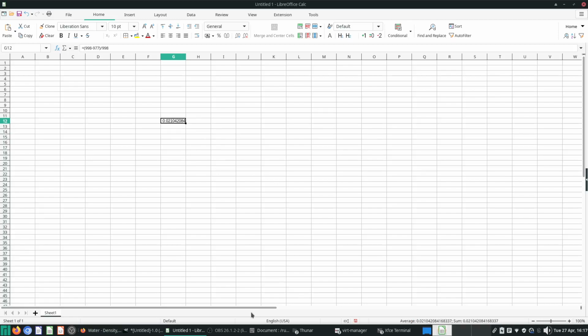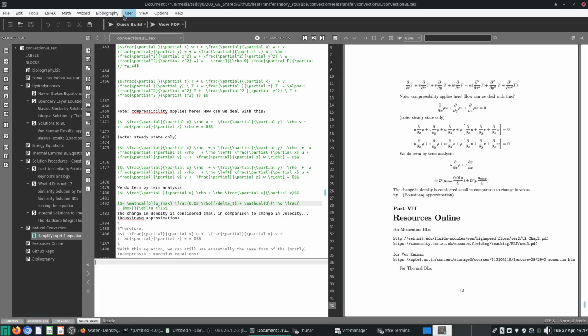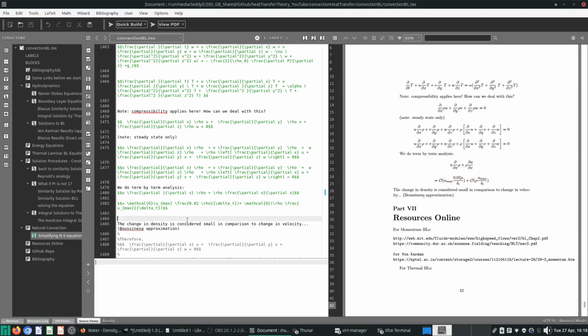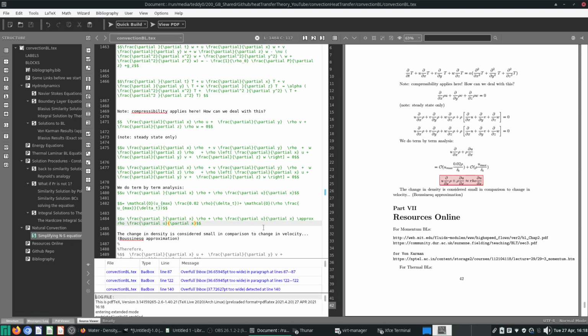It's not completely negligible, but compared to this term over here, you can just strike this thing off. If you have a 70 degree plate, and your water density changes due to temperature, we won't see a very big change. So we're just going to use that water example. I just put 0.02 here. Since this change is small compared to what we have here, this term is approximately just this. We can ignore, and we will ignore the first term.